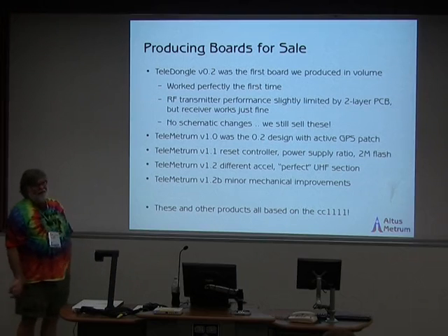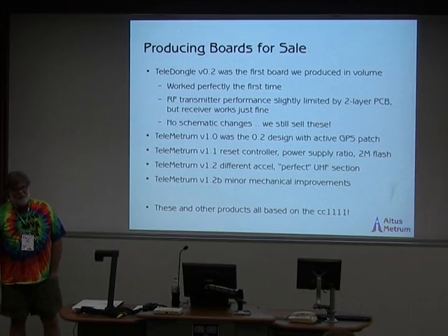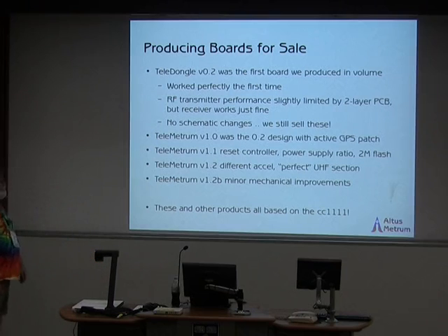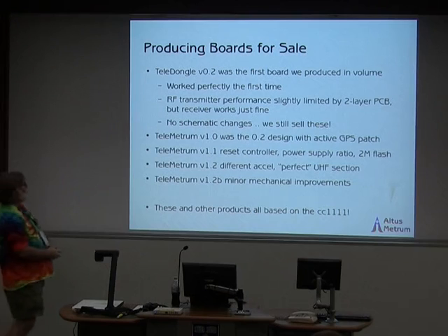And the LEDs are out in the version. You're right, there's a mechanical change to spread the LEDs so they're a little more visible. Certainly, and I did improve the design of the SMA edge launch footprint so that we solder it on the back side too, not just on the front, which is mechanically a lot stronger.